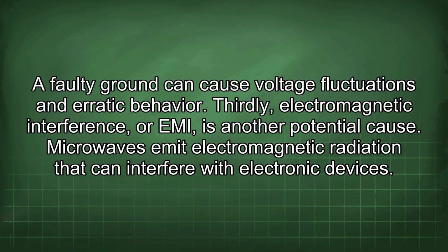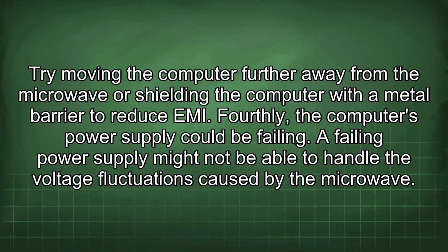Thirdly, electromagnetic interference, or EMI, is another potential cause. Microwaves emit electromagnetic radiation that can interfere with electronic devices. Try moving the computer further away from the microwave or shielding the computer with a metal barrier to reduce EMI.